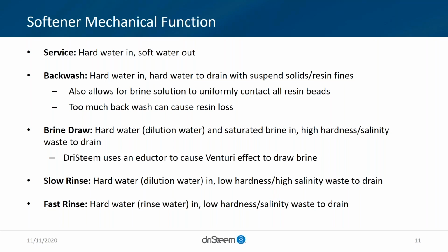The last two steps of this regeneration process are essentially rinsing out that salt water, right? If it's salt water, you've got that chloride aspect that you definitely don't want to translate downstream. And most processes that you're protecting don't want additional dissolved solids anyway. The one note is after fast rinse, if it's a single tank softener, it'll go back into the service mode. And if it is a twin tank system, the system would go into a standby waiting for that first tank to go into regen.